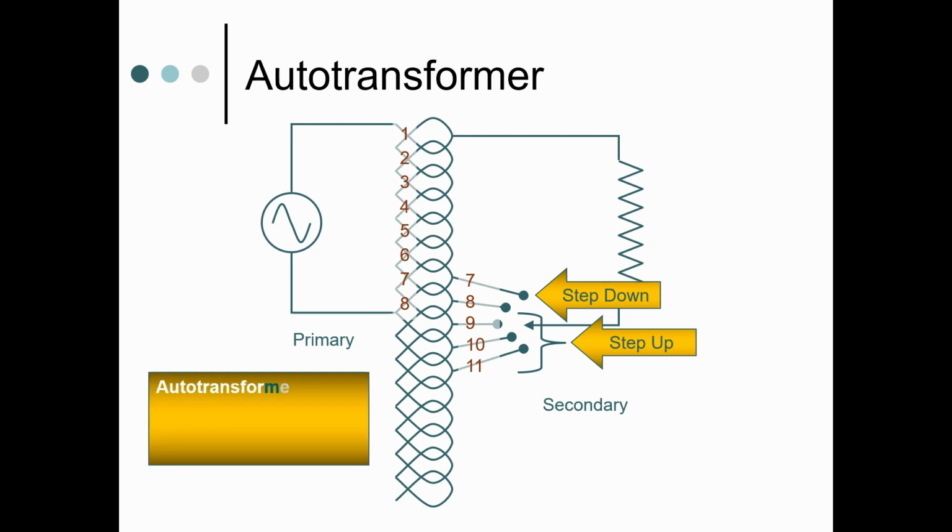Autotransformers are mostly used to make a device that can offer the user a selection of voltages. Autotransformers are limited to stepping up the voltage by a factor of 2 times and are generally used to provide kV selection in the X-ray generator. The kV selector autotransformer is in the circuit before the voltage is stepped up to kilovoltage levels.